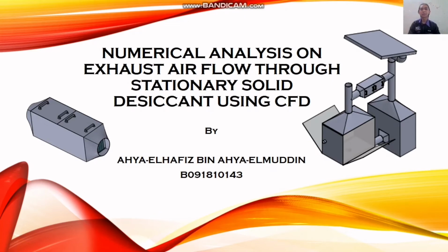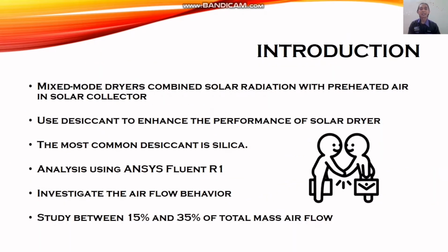So today I'm going to present my final year project titled Numerical Analysis on Exhaust Airflow through Stationary Solid Desiccant using CFD. As an introduction, the project used a mixed mode dryer combining solar radiation with preheated air in the solar collector. It used desiccant to enhance the performance of the solar dryer, and the most common desiccant used is silica gel. The analysis runs using ANSYS Fluent R1, and it is used to investigate the airflow behavior.